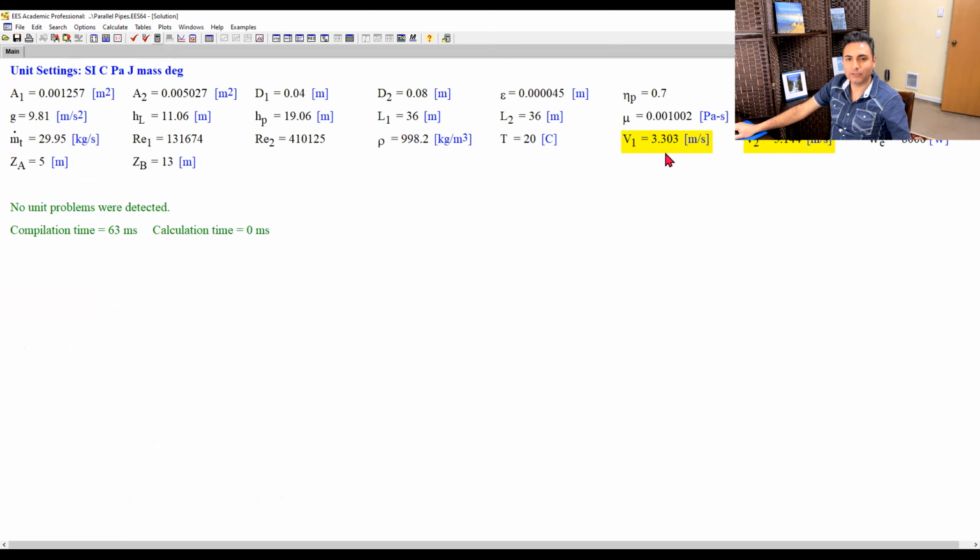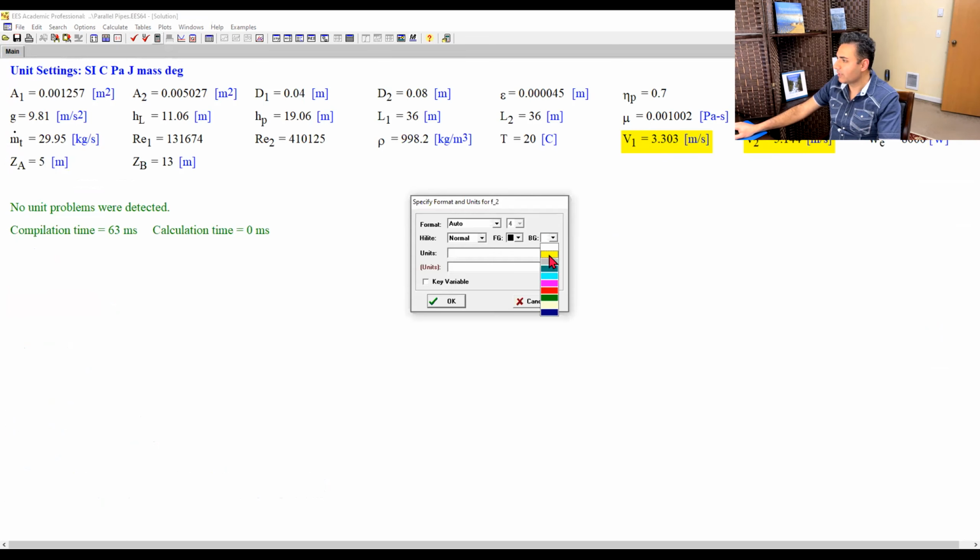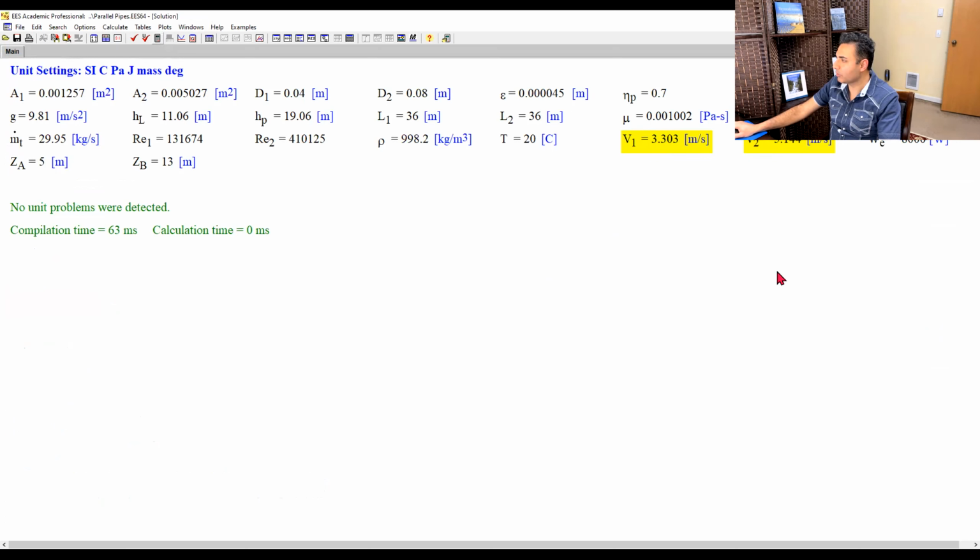If you go back and look at those numbers, they are still pretty close to the numbers you wrote down. But let's see what the actual value of friction factor is. I predicted 0.02 and 0.03. I got 0.018 and 0.022. And the value of total m dot that the first solution, the fake solution, got us was 26. This is 29. That is close. I could have never known this.